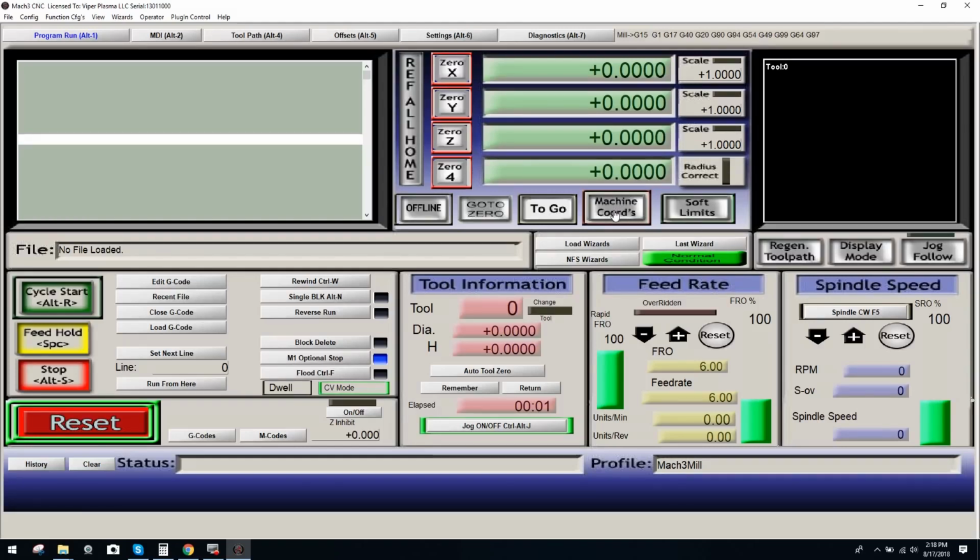entered Mach 3, this is your offset position, G54, and you're in 0. In this case, all of your axes are representing 0, so that would be your bottom left corner of the screen, arbitrarily, so to speak. You can set that position wherever you'd like using the process I'm about to show you, but overall, that's where I would start my G54 personally.